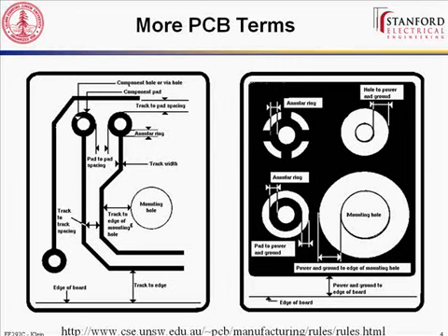So if this layer is just in between, then how do we get solder? This is a layer in the middle of your board, and the question is, how do you get the solder into it? So you have holes that are drilled through, and these holes are plated. So if this was a component hole right here, the entire hole itself is plated in copper. And you remember that you have to have this annular ring on every layer.